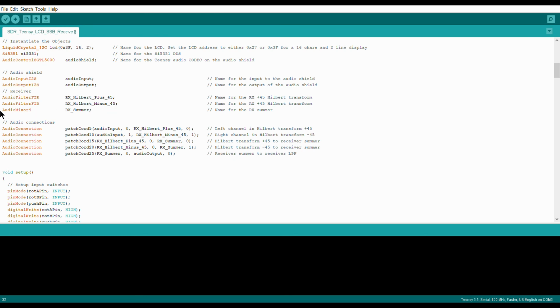We're also going to use a mixer, and you recall from the previous video in the terminology used by the Teensy audio library, a sound mixer essentially sums together different sounds on the input and then sends on the output that summation. So for us it's a summer. So I'm going to call it here, just to make it a bit easier when you're reading the code, receive summer.